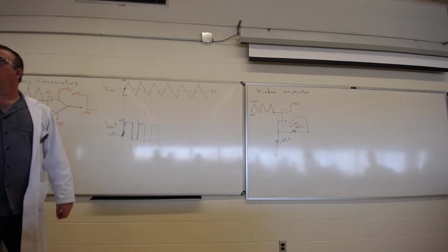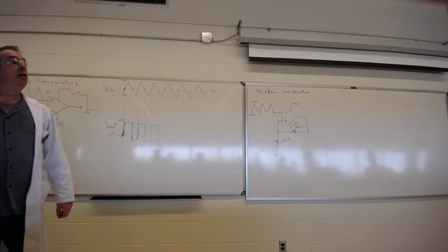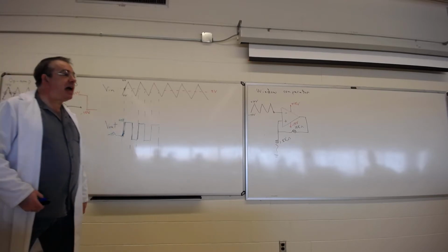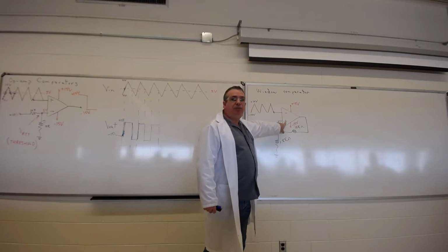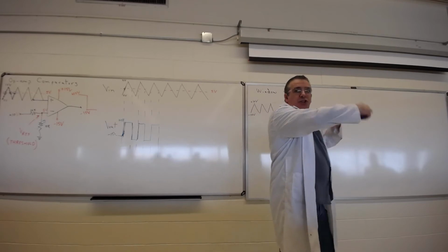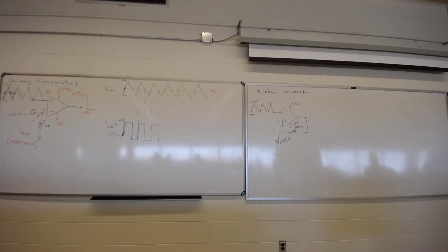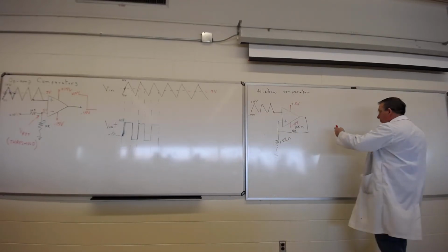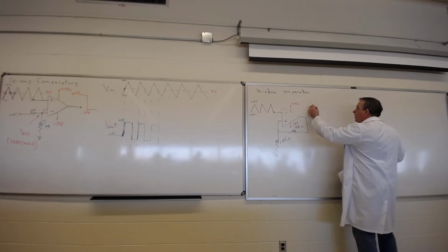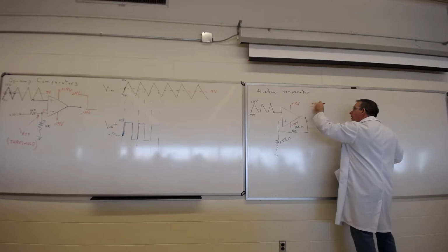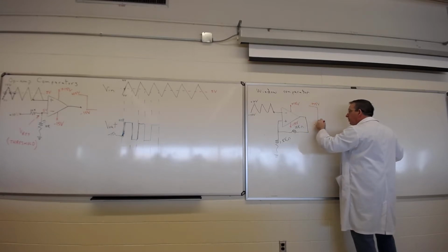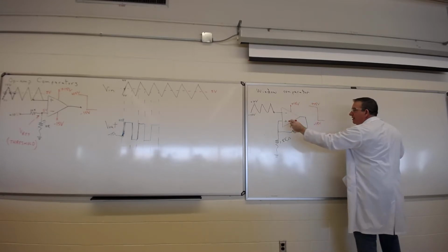Because you've got your input. It's negative feedback? No, no negative feedback, exactly. It has to do with this sign right over here. You see, this is positive feedback. That doesn't work. Positive feedback creates a snowball. So the output is going to saturate. It's either going to be plus 15 or negative 15. This thing doesn't amplify. This is positive feedback. This is the key right here.